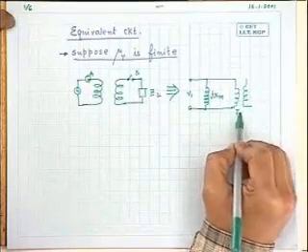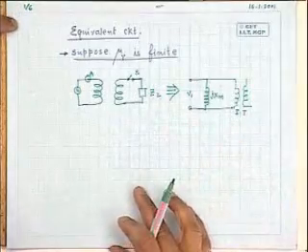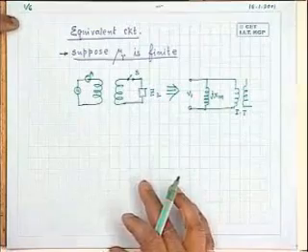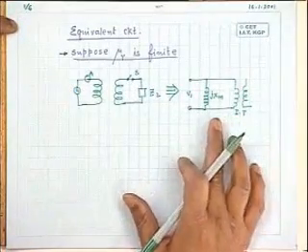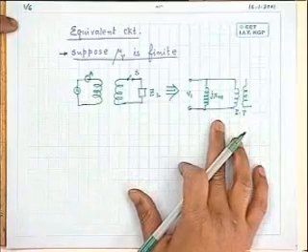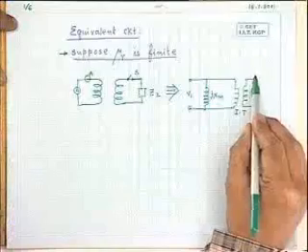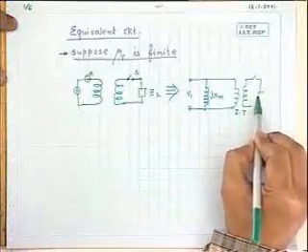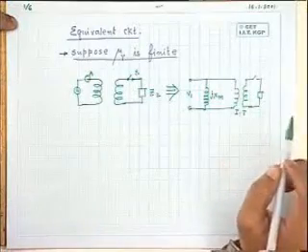This portion is the ideal transformer. So a practical transformer becomes equivalent to a reactance connected across an ideal transformer on its primary side, when you want to consider mu r to be finite, when you want to take that into account. And we have seen that it satisfies all the known things that we have discussed.